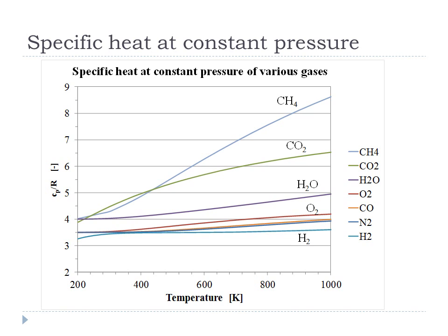So you have the potential with methane to have a very, very large C sub p once you get to the temperature in which all of those modes are being activated. But when you combine all those, it just kind of lucks out that between 300 Kelvin and 1,000 Kelvin, the range that would be of interest mostly for methane, we don't need to go much above, unless you're reforming methane, you don't really need to go above these temperatures. And what we find is that it's a linear fit through this range.